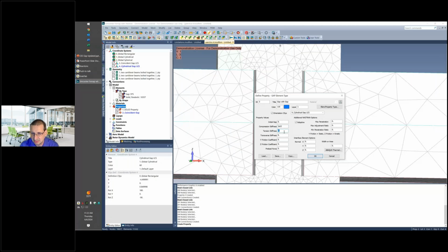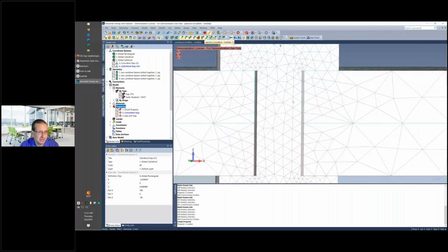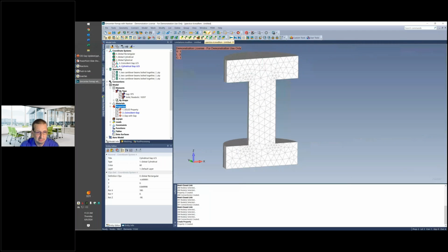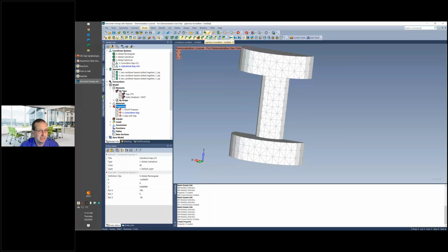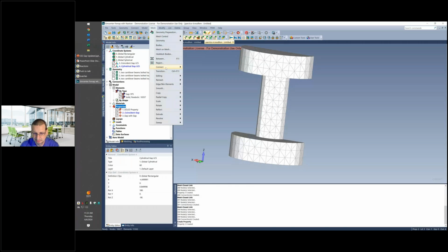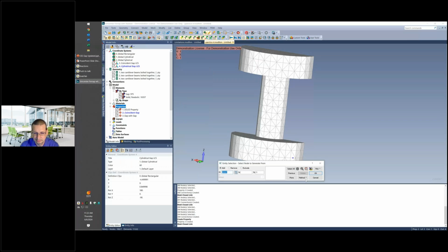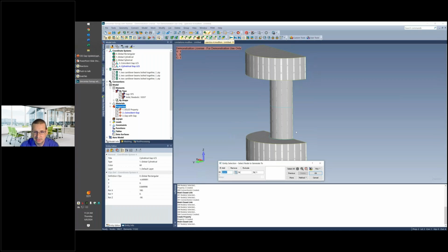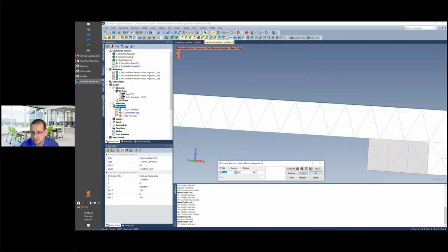Fun stuff. I'm using basically the same values, 0, 1, everything. The only difference here is a cylindrical coordinate system that I'm going to use for orientation. Click OK. Cancel out of that. Now we should be able to define our gap. You'll notice that I left the initial gap blank. I'm going to take advantage of the tool in here and have it automatically figure that out for us. Oh, so it's off. Click, click. Okay, now we should be able to reverse this just to make everything that much easier.